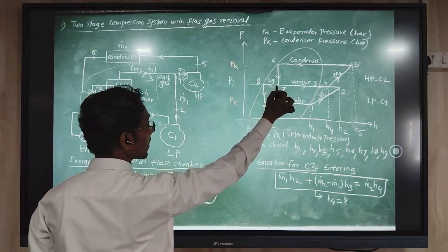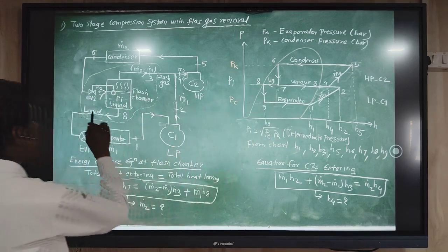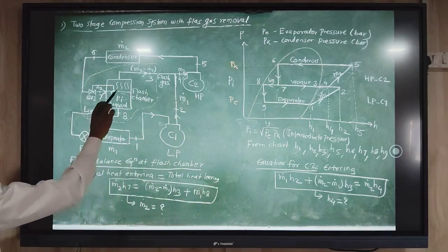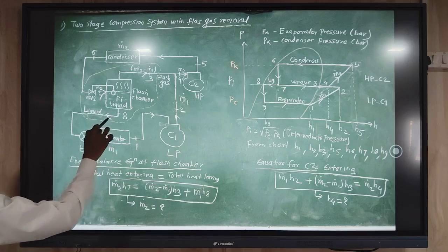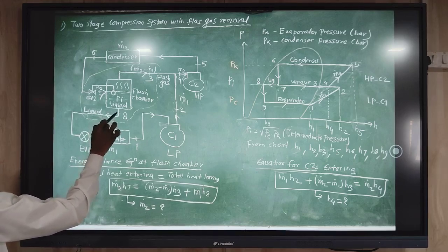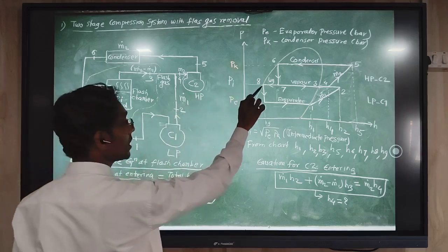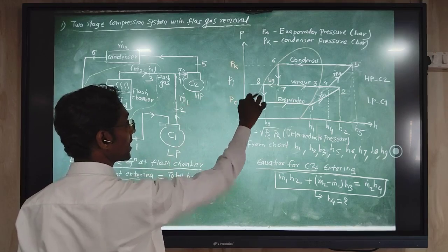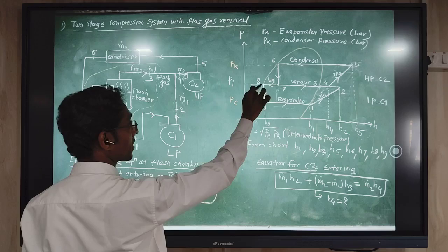After that, the refrigerant is separated into two parts, vapor and liquid, because the line passing to the evaporator is taken from the liquid side. So the refrigerant passing to the expansion valve is in a saturated liquid state. That is why the 8-9 process starts on the saturated line, point 8 being saturated liquid.